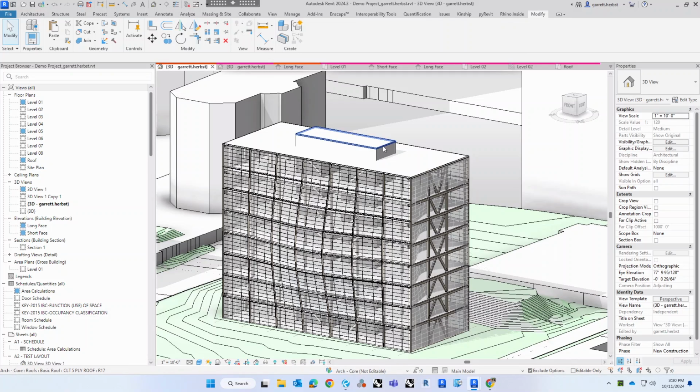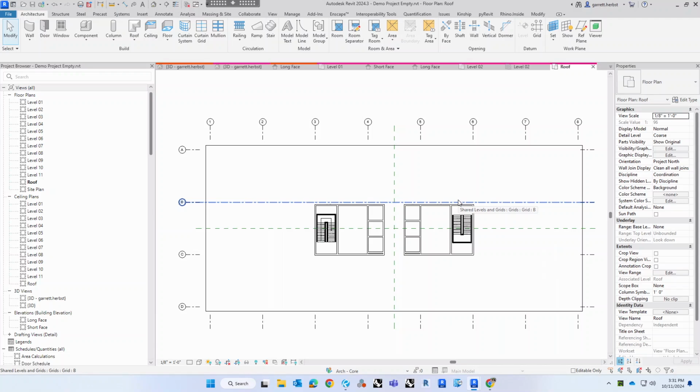Where was I? Yeah, so just make sure that your roof is accessible. That means you have to have either a stair extend to the roof or a ship's ladder of some kind, preferably a ladder for all of your maintenance people. And then make sure that you have clearance above your elevator for the machine room and for its runoff.